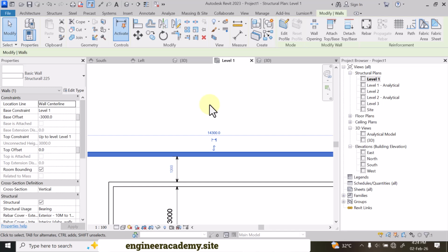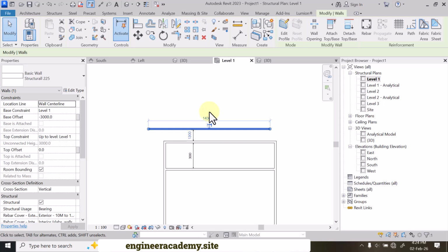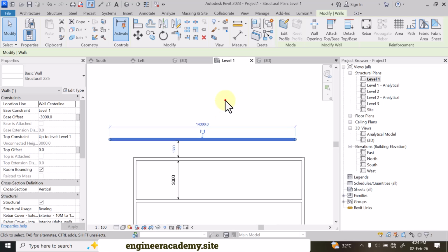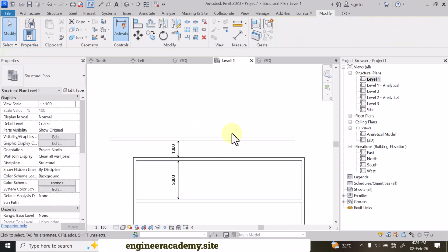Before we wrap up the class for today, let's go to how to copy in Revit Structure. The icon beside move is copy. Okay, this is copy. Assuming I want to copy, it could be a structural wall or any object in Revit Structure, you want to copy it. So all you need to do, the first way you can follow is you can select the object first.